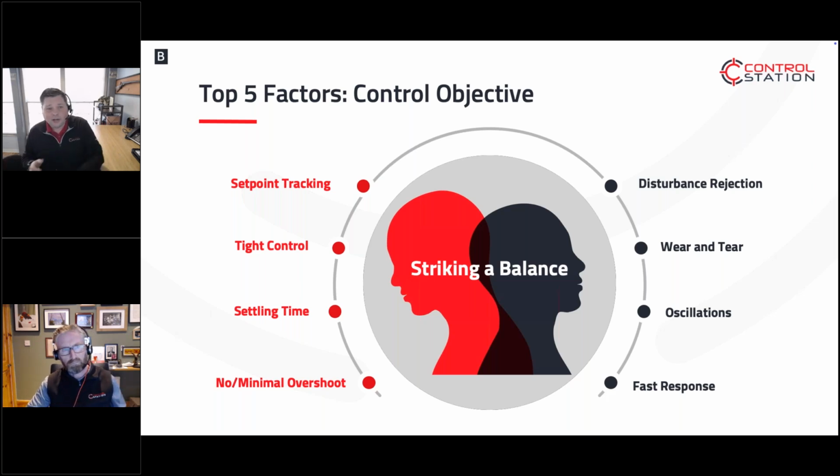We're just going to go tune the loop, right? I can guarantee you, a lot of times in commissioning, you go in, just get the darn thing running, right? But just running isn't good enough. You need to figure out, why is that control loop there? What is the goal? You've got to have an end game in mind. What does good control for this loop look like when you think about the bigger picture, right? Defining that objective gives you the ability to go and tune the loop appropriately.